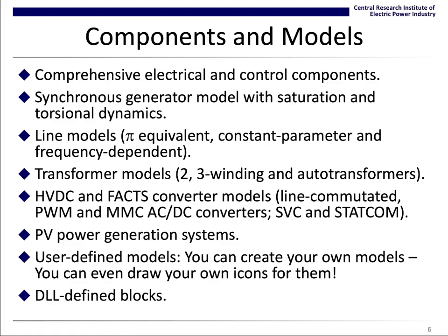If you enable the torsional dynamics option, then you can use it for subsynchronous resonance studies too. XTAP has various kinds of line models: pi equivalent model, constant parameter line model, and frequency-dependent line model. The parameters of those models can be generated by XTLC.